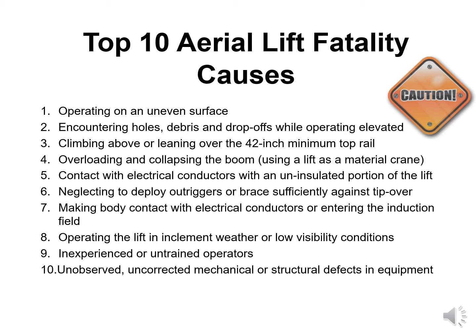The top 10 aerial lift fatality causes. 1. Operating on uneven surface. 2. Encountering holes, debris, and drop-offs while operating elevated. 3. Climbing above or leaning over the 42-inch minimum top rail. 4. Overloading and collapsing the boom using a lift as a material crane.